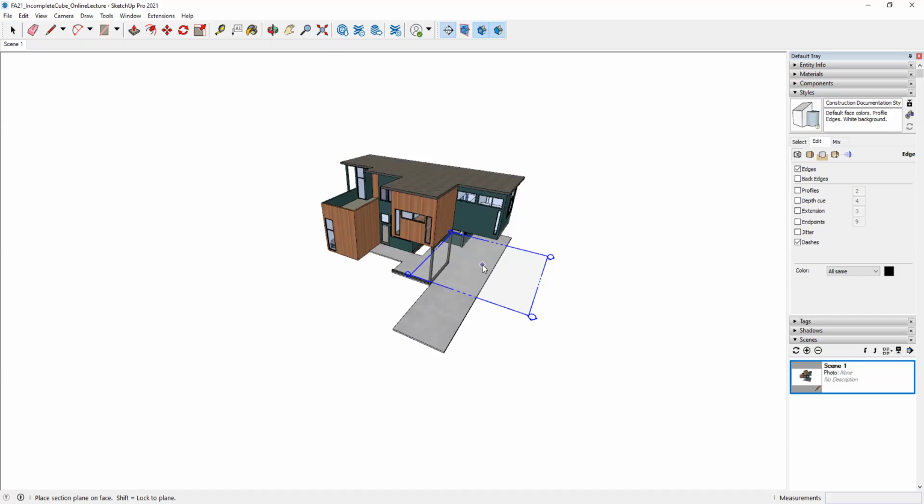There are different components to a floor. We have floor joists, we have the subfloor, then there might be an additional subfloor based off the material that you're using. And then finally, the very top surface, what we actually see, is known as the finished floor. Floor plans are horizontal cuts that are taken 4 feet above the finished floor of that floor. So if I'm standing on the second floor, then it's 4 feet above the finished floor on my second floor. So that's what a floor plan is, and it's a plan that is looking down.